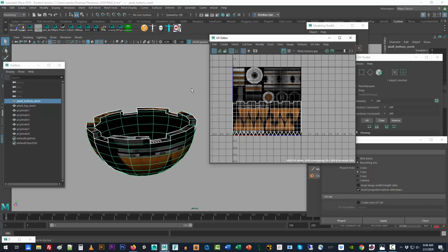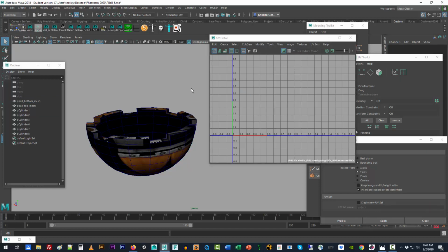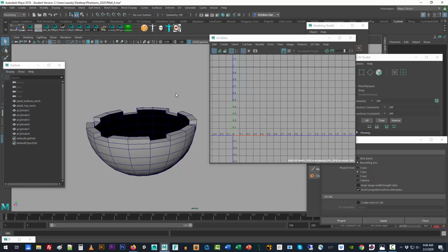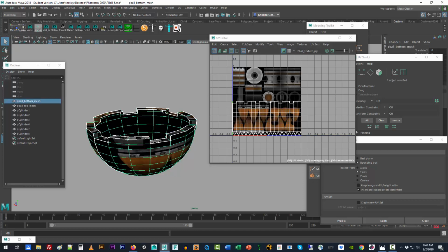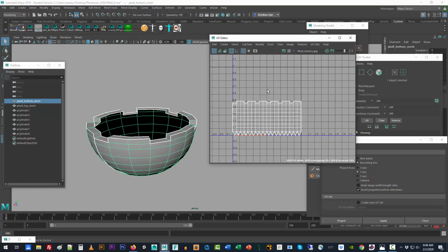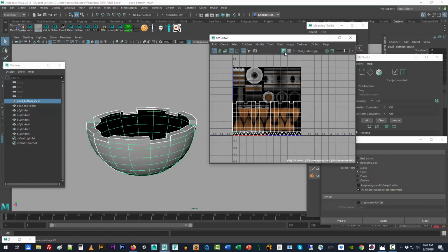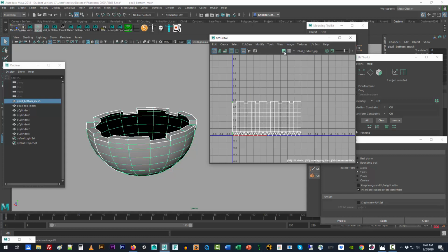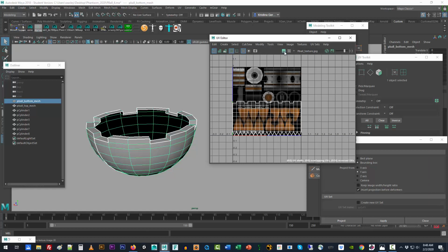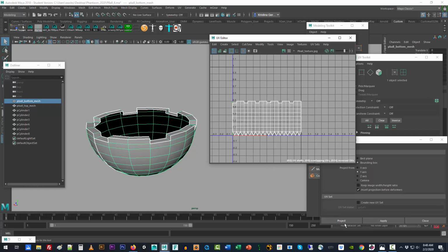Now, majority of the time we don't really want to bring this in because it's quite distracting, but when we're ready to, so I'm going to hit 5 here in the modeling window, not 6, which is textured, but 5, which is hard shaded. And I'm going to come up here to the UV editor as well and turn that image off, but I have it connected now, so if I ever want to see if I'm aligning things correctly, I can just press this little icon here and it'll pop on. So let's forge ahead with texturing up, cutting up the Phantasm Ball to retroactively fit.